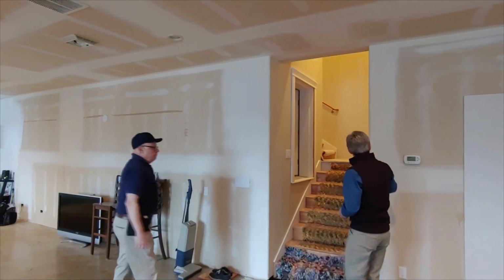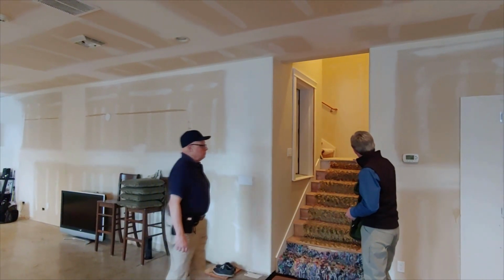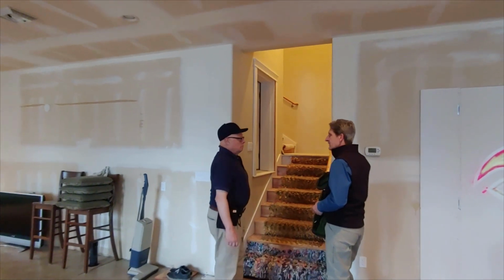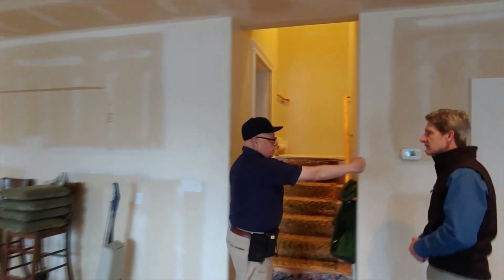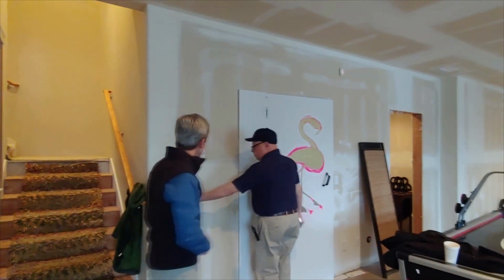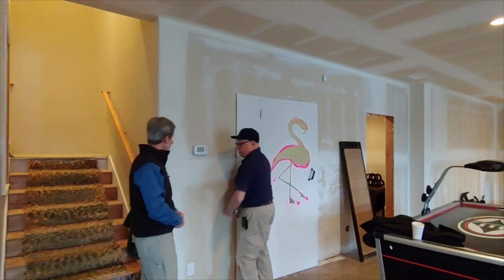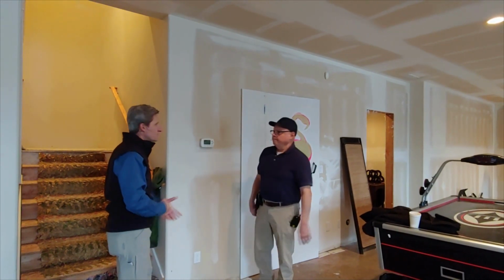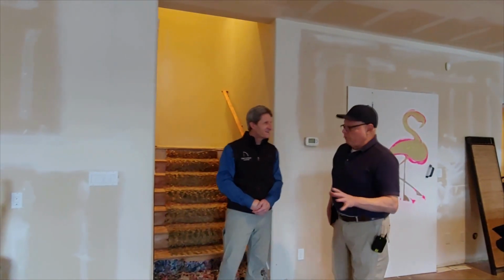That's the easiest way. Now there is a wall that divides the stairwell and this closet alcove here. How would you go about that? Same way. Come from the inside and then bring the tape around on the outside, measure back over, locate this area, and then bring the tape back and get the thickness of the wall. Well, that sounds pretty easy. It's all about points of reference.